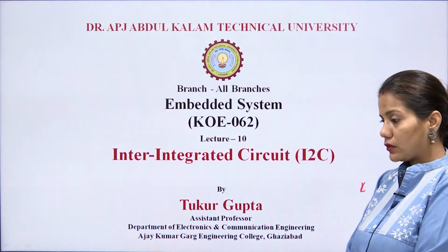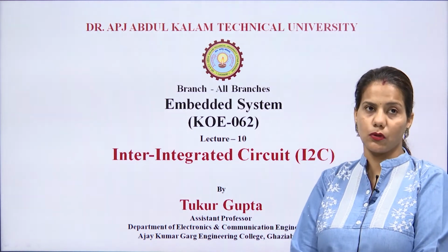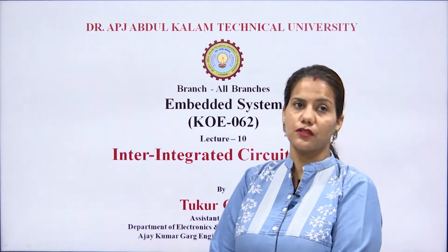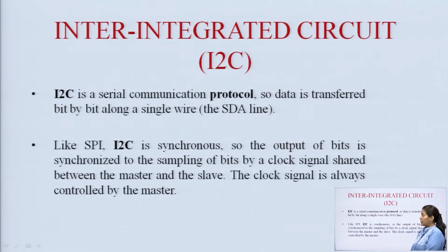Today the topic that I am going to cover is Inter-Integrated Circuit Communication Protocol, that is I2C communication protocol. So, basically I2C is a serial communication protocol. Data is transferred bit by bit along a single wire. In serial communication, one bit at a time is transferred from transmitter to receiver side, and so is the case with I2C also. The line which will carry the bit is the SDA line,